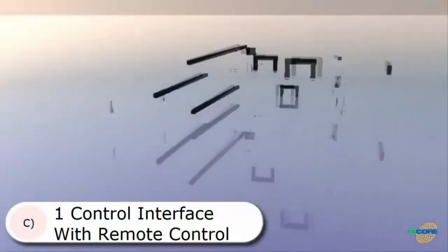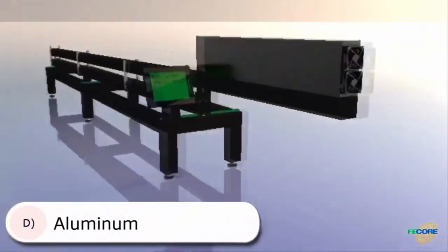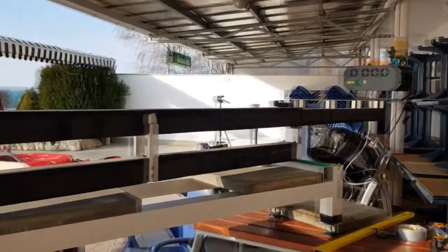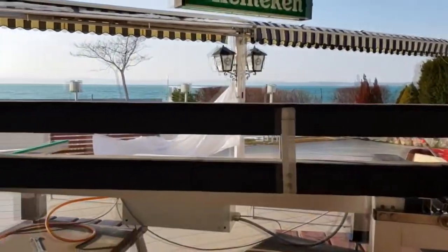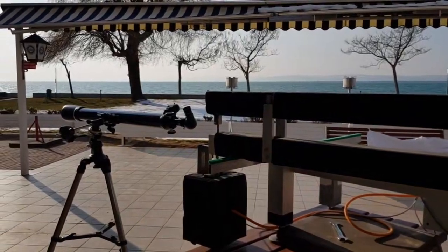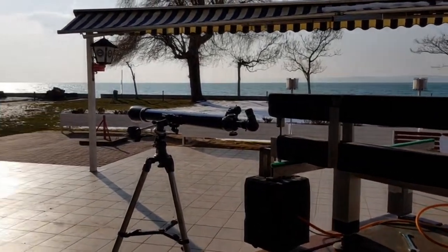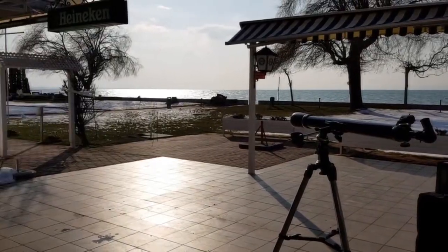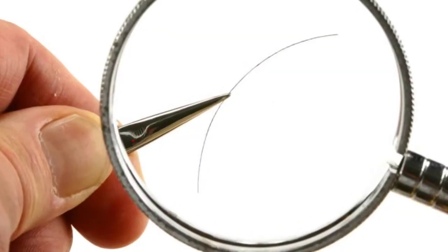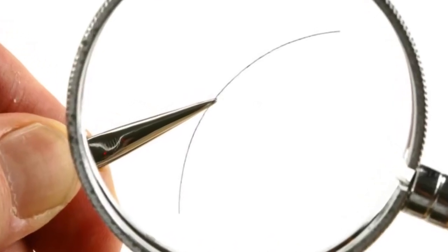This was accomplished with two high-tech stepper motors capable of making movements as small as 1/10,000th of a rotation. That is equal to 36 1,000ths of a degree. This rotation movement was transferred to a bolt with fine threads 1.5 millimeters apart. That meant the rail where the laser was attached could be moved in steps of 15 100ths of a micron. That is less than 1/1000th the thickness of the thinnest human hair.